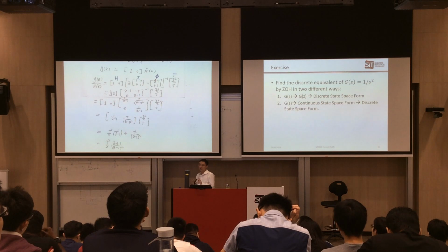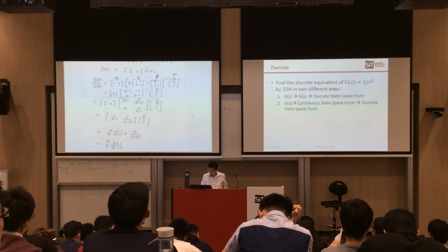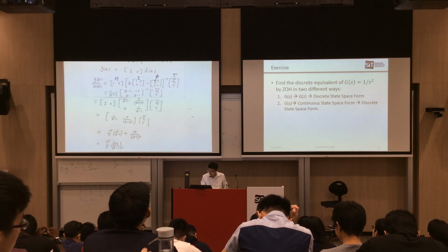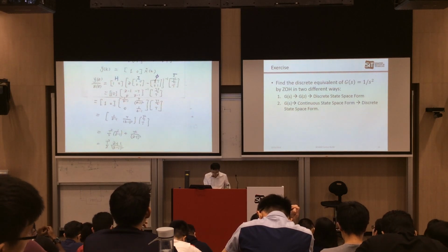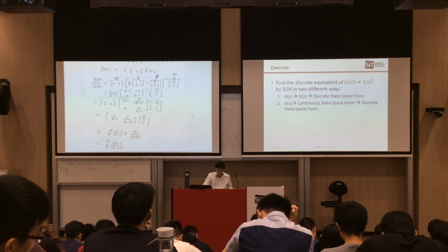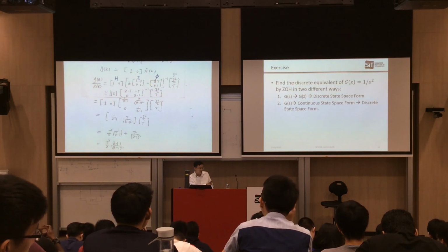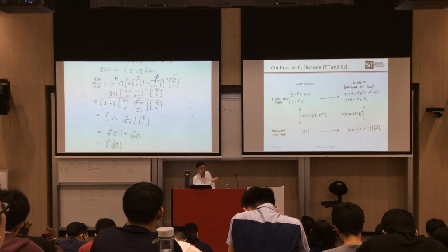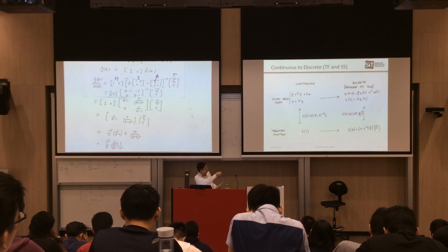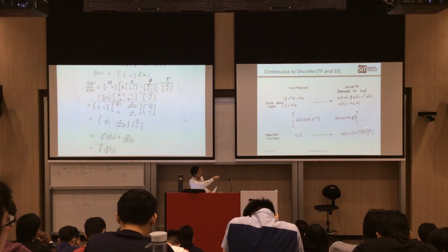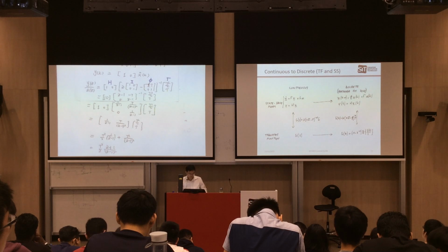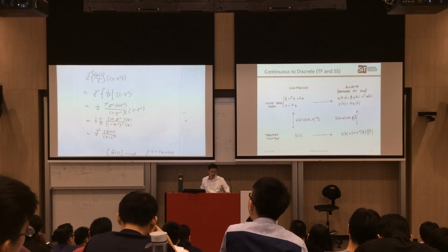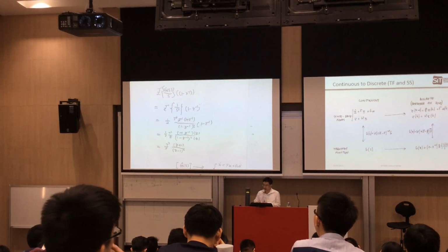Now I have shown you one cycle, right? Any questions before we move on? Now we have shown you one cycle, but G(s), you get your space, digitize your space, you get your G(z). So you finish one cycle, right? Now, why don't we do another one? G(s), digitize, get your G(z), then you also get your digital discrete function. This from your G(s) to your G(z) also can be considered one of the solution to the exercise question, right?